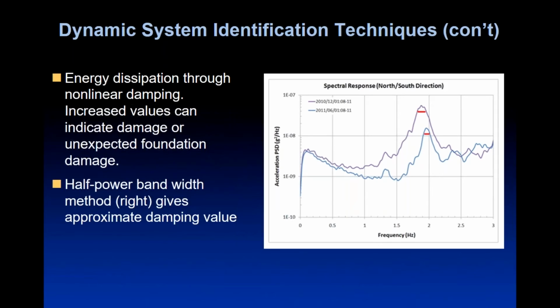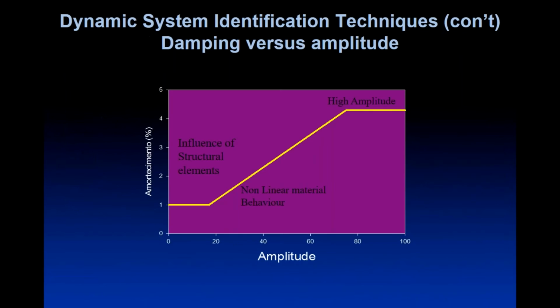They knew this at that stage. That's why we went in. And they put new shear walls in to try to negate this effect from the trains. The new shear walls cracked because they were not put in the position which would have been optimized to reduce this. If we'd been there beforehand, then we would have said to them, this is where you need to stiffen up the vertical response.